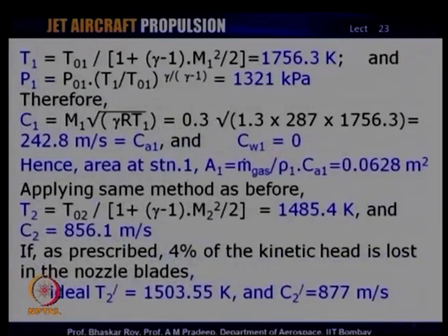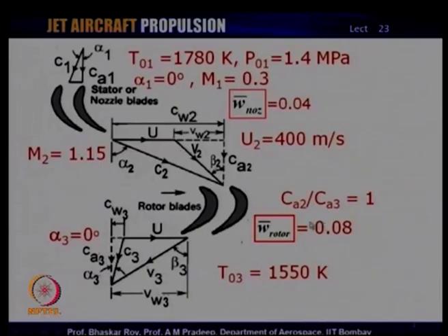Let us take a quick look at the velocity triangle. You see, corresponding to our calculations, C2 has been prescribed clearly as supersonic. We got the velocity value, and we got the V2 velocity value. When we converted V2 to M2 relative, this is clearly subsonic by the local flow conditions, and this is exactly what has been achieved through this velocity vector transformation, that the exit velocity here can be clearly supersonic, but the entry here would be subsonic.